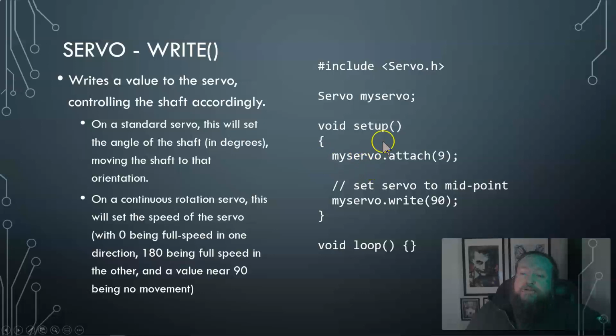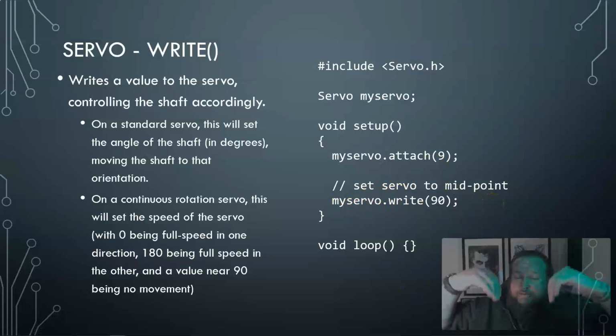But either way, for this example, in setup it means it's connecting one servo to pin 9, and then at startup, it's telling the servo to move to 90. And there's no other delay. So I'll explain this again here. It's sending its signal, and this is your controller, and then that other controller for the motor works asynchronously at the same time, and this one will be moving while this one continues on.